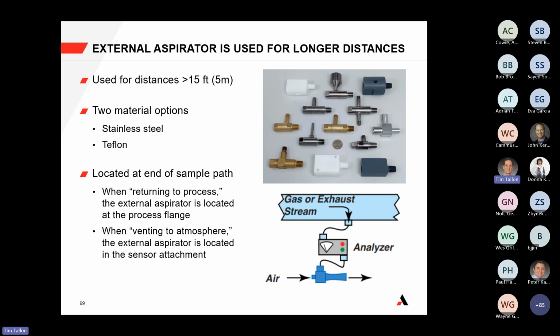If you have a special application that is a higher or lower pressure, then we typically install our analyzers right at the flange. You can contact us and we'll get with our engineering team to consider any pressure issues. There are different options available that are very powerful, and we can actually pull the sample if it's negative pressure, or we have other options if it's a positive pressure.